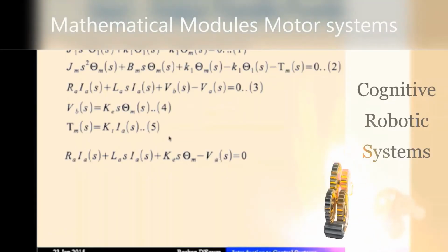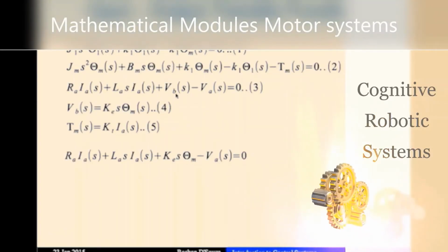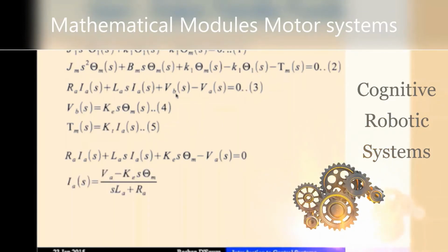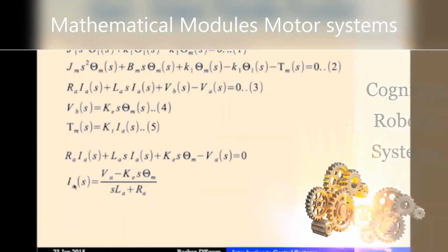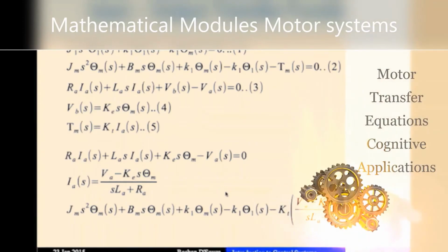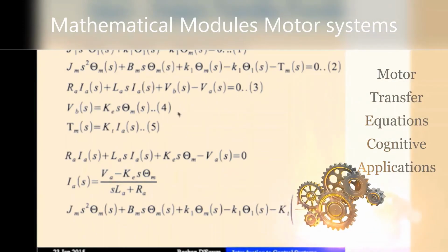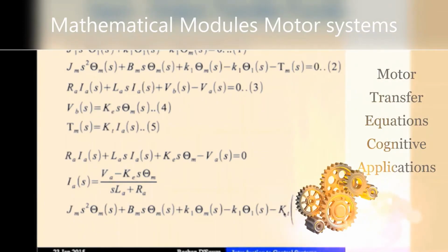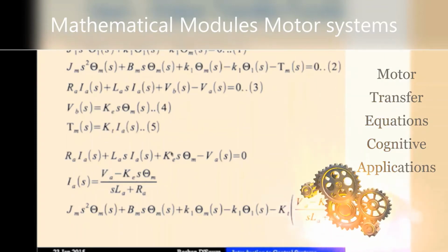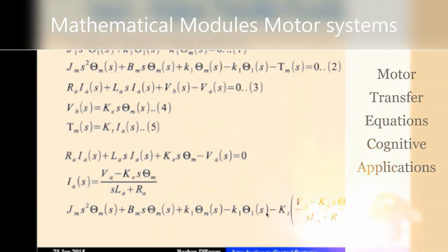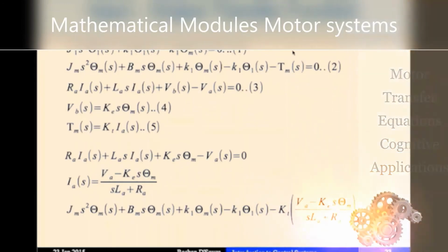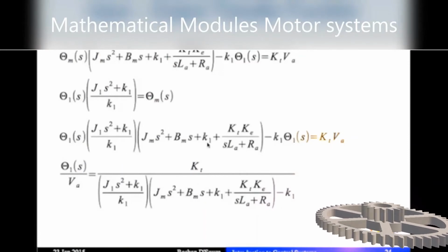The motor voltage and revolutions per minute are obtained at different duty cycle rates. As the duty cycle rates increase, more voltage is applied to the motor. This contributes to the stronger magnetic flux inside the armature windings and the increase of RPM.